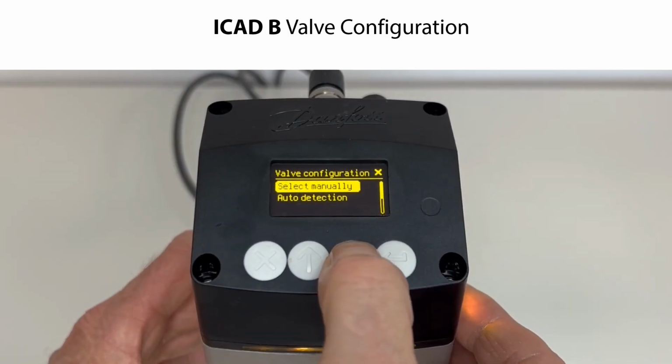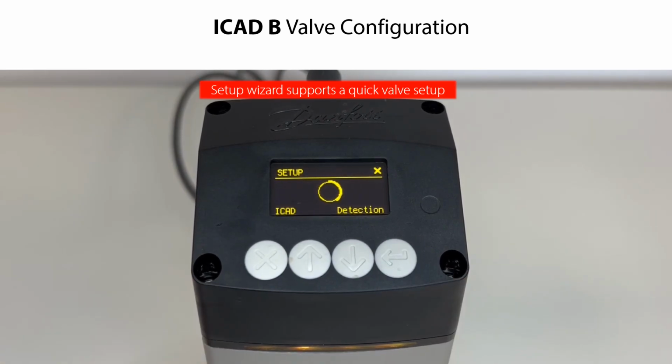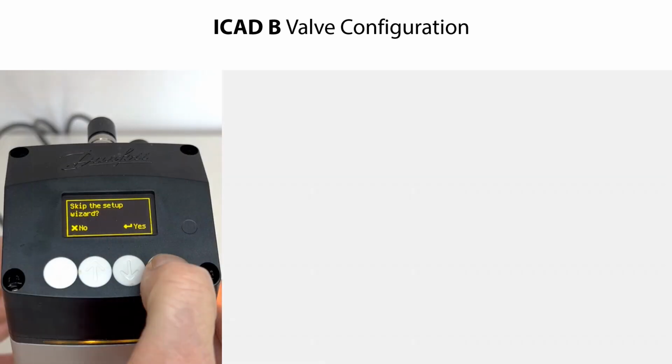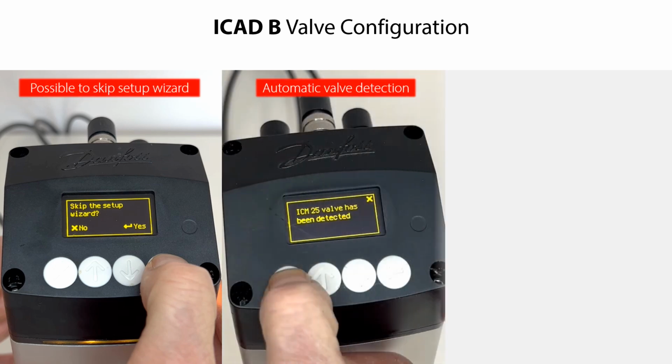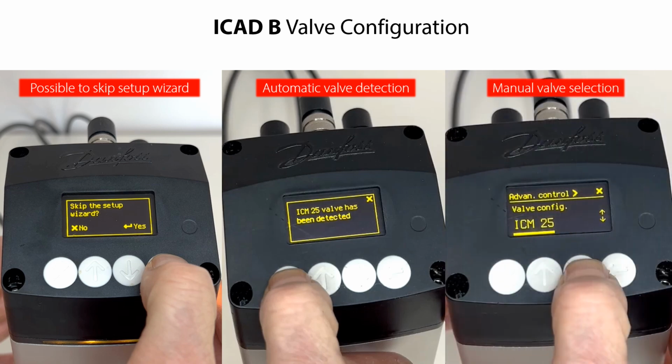Now, as shown earlier in this video, after power on, the ICAD B setup wizard automatically guides you step by step to do a valve configuration so that you can operate the valve with the ICAD B. However, as also mentioned, it is possible to skip this setup wizard, or whenever needed, alternatively do an automatic valve detection or do a manual valve selection in the ICAD B.